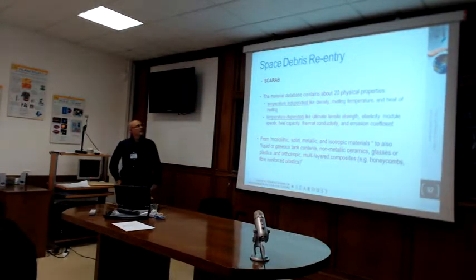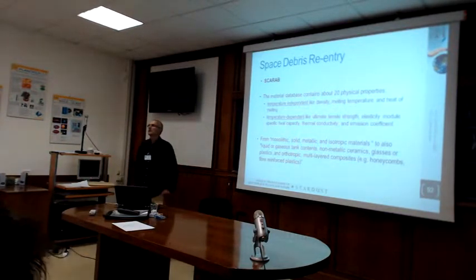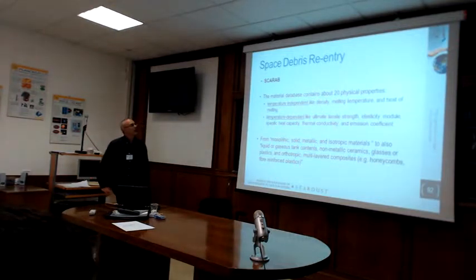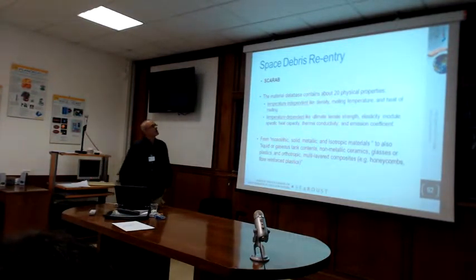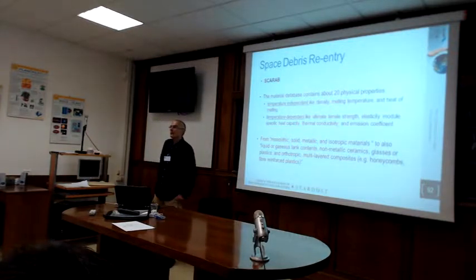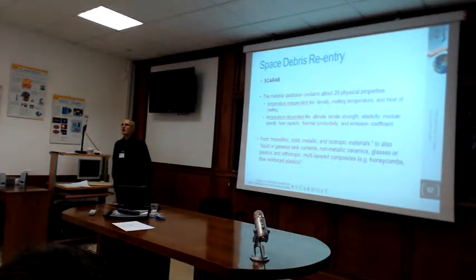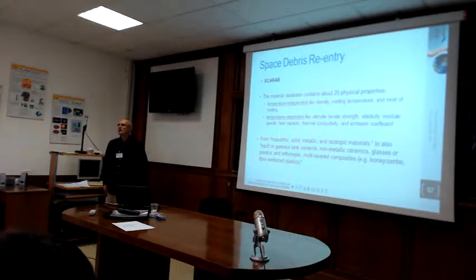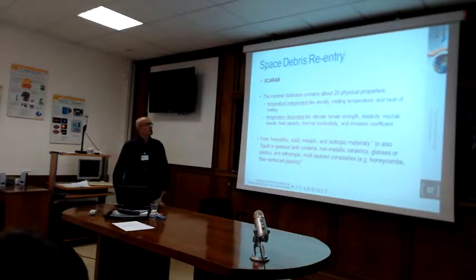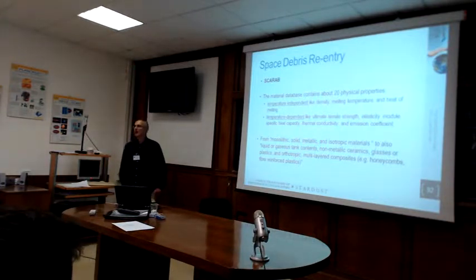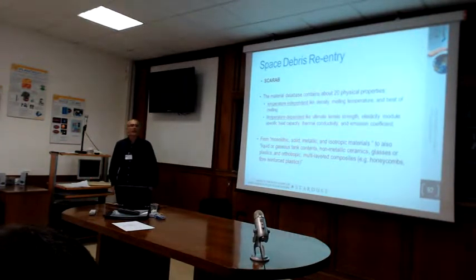So, the material database. Scarab comes with a quite well-defined database of materials, and all the physical properties of the materials are both temperature independent and temperature dependent characteristics. A characteristic that makes it quite unique is that the people who implemented it do not only consider the solids, but also what is inside, for example, liquids in the tanks. And they do not only consider metallic elements, but also try to model the mechanical and thermal behavior of non-metallic and non-isotropic materials.